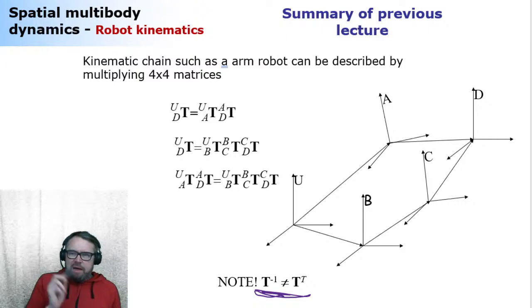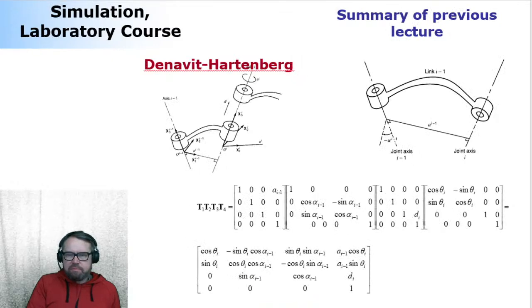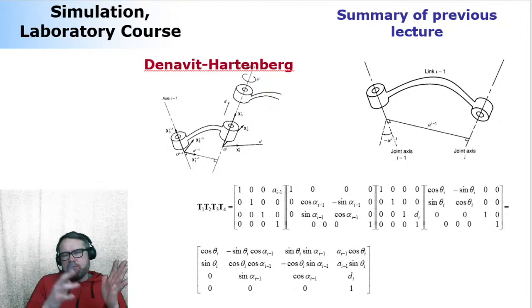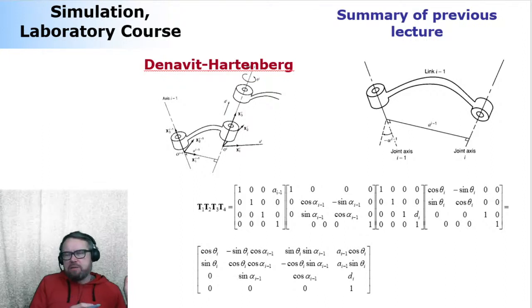And a week ago, we learned that there's this technique called Denavit-Hartenberg, which is exactly this 4 by 4 matrix representation. It goes in such a way that you predefine 4 parameters. You're predefining the 4 possible ways that successive rotations, successive coordinates, are connected together.